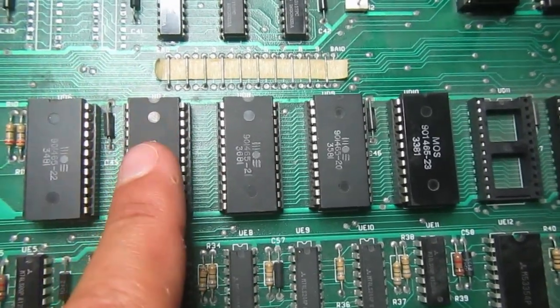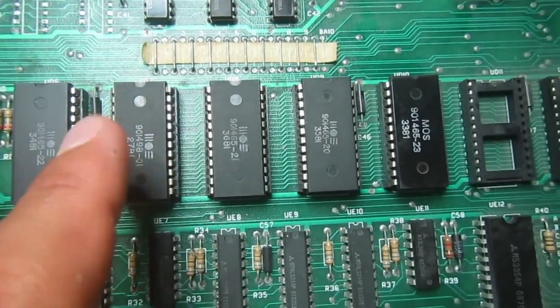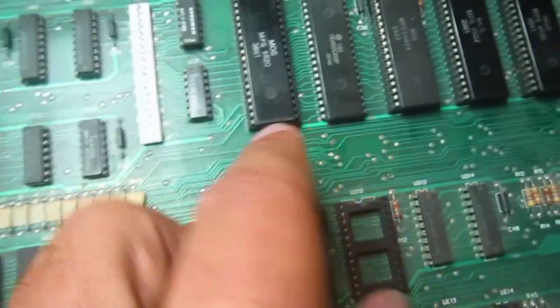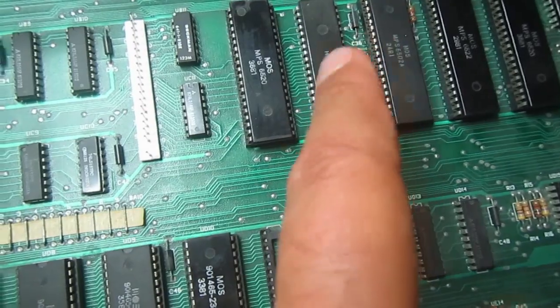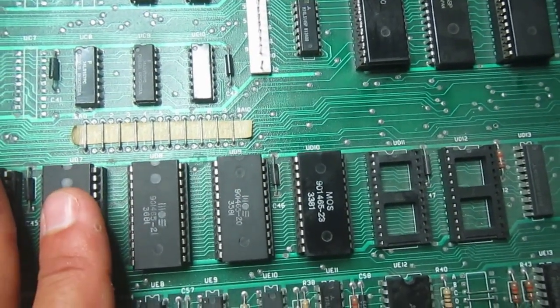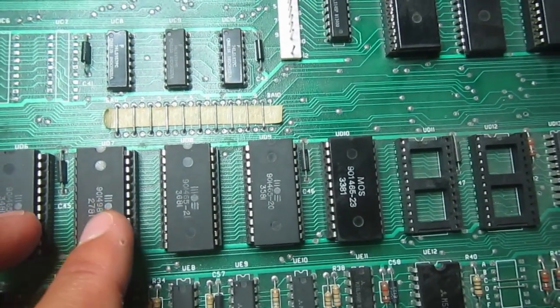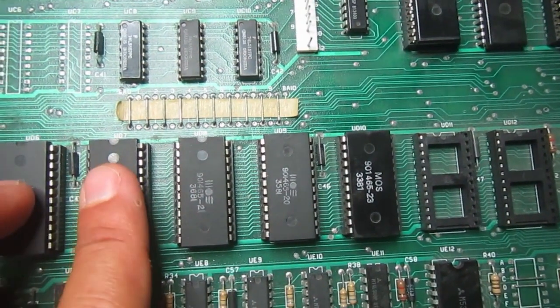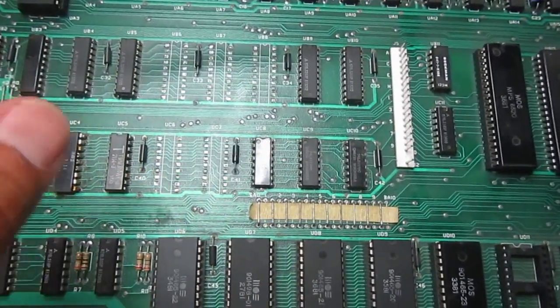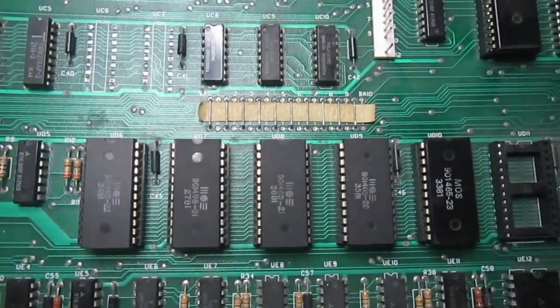I will link in the description a place where you can download some editor ROMs that can program the CRT controller to output more useful frequencies for normal PAL or NTSC monitors, and use that if you have such a universal board without the proper 12-inch monitor. So now that we can see what happens on the screen, let's begin.